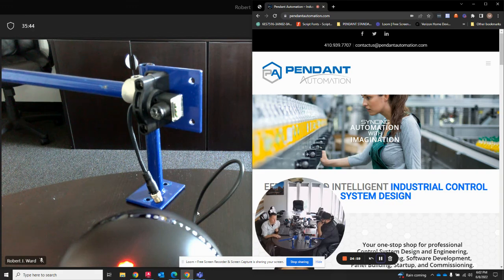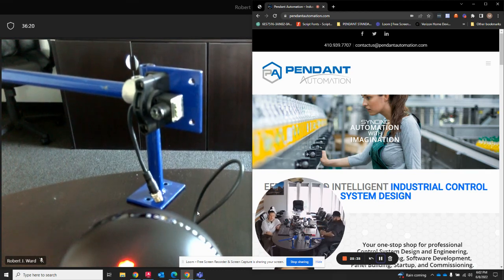absolutely no drill. They don't have to have a 1/4 inch bit to drill another hole through the conveyor, take this out, re-put it in, tighten it down, and then realize, oh man, that wasn't enough. I need another inch, and now they have to do the whole process. They can go there with an Allen key, loosen those up, fold it back some, fold the photo eye back some, and now they've already moved it 2 inches, no problem. And it's super versatile. Yep. And at Pendant, we use this bracket for 99% of our applications.